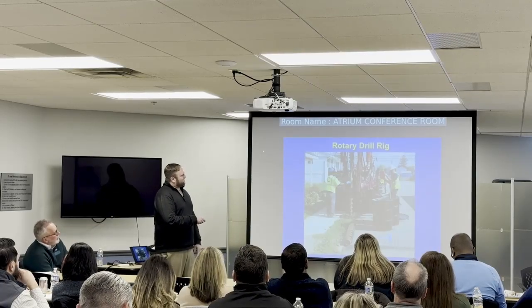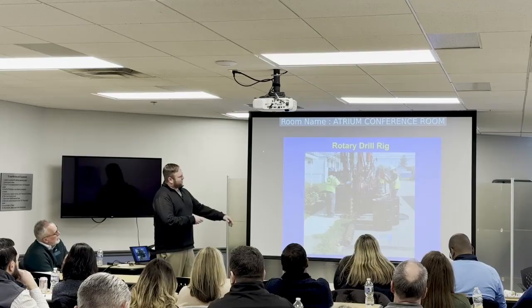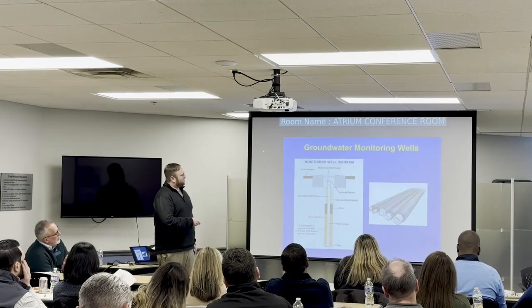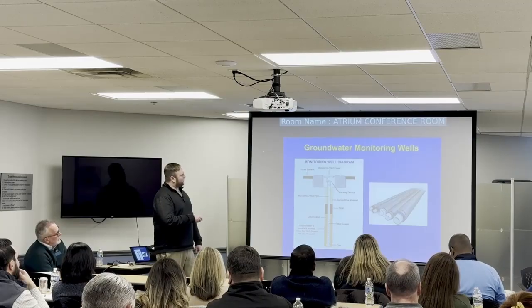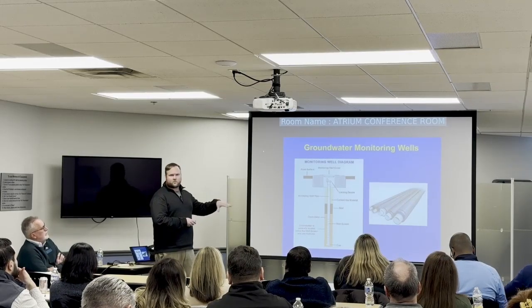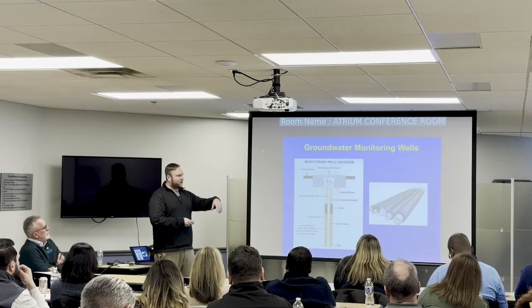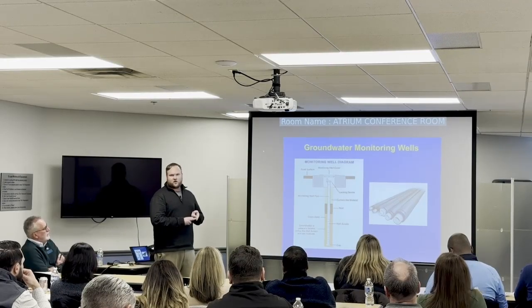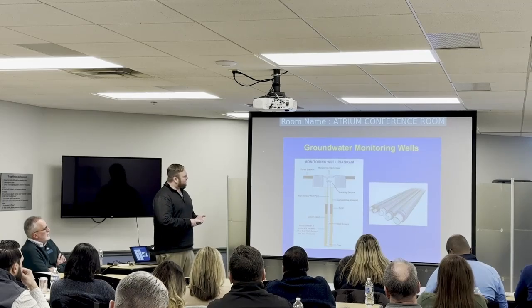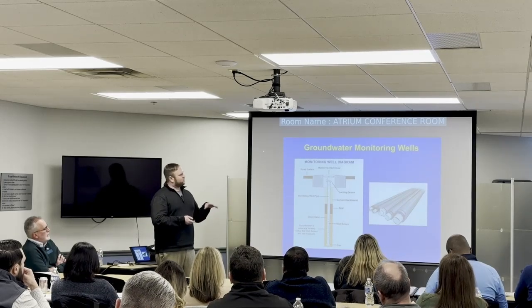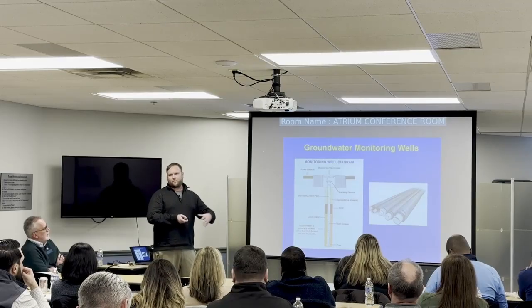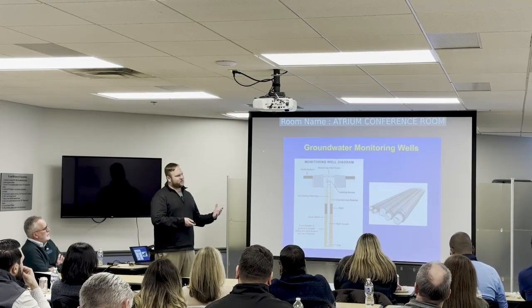Rotary drilling, another example, putting in a well, generating more soil spoils. Groundwater monitoring wells, essentially this is a permanent well we can put in to be able to come back and access this sampling point multiple times to continually monitor groundwater. You can use them to study hydrogeology. You can also use them for remediation methods if necessary at sites. We use the term permanent well a little liberally because of course you can come back and remove that. Once you're done, they can be properly abandoned.